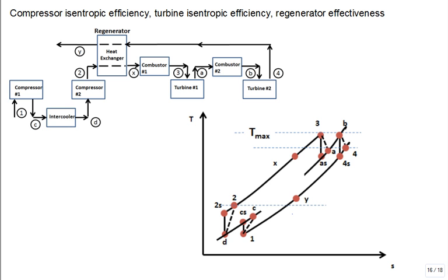If you wanted to, you could take a look at a pressure volume diagram, and visually, remember we were taking it up the whole way to go from this low pressure to high pressure. If you take it up to some intermediate pressure and then cool it off at constant pressure, it'll kick over, and then continue the compression.